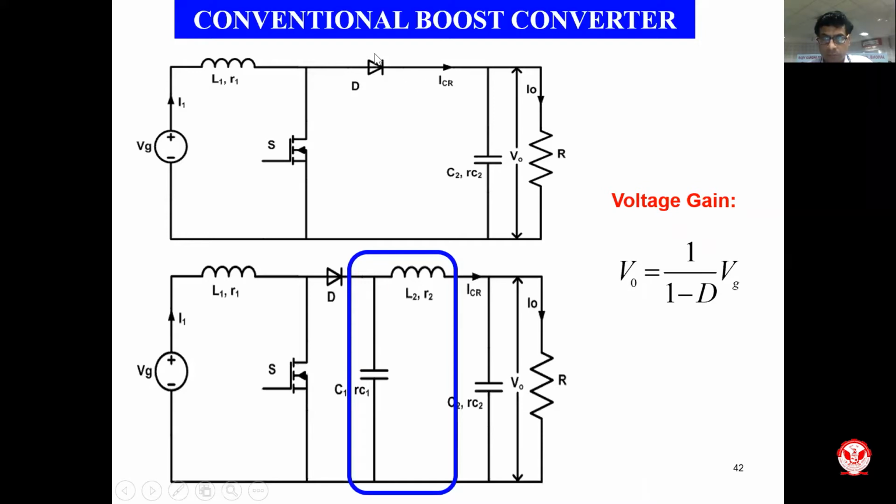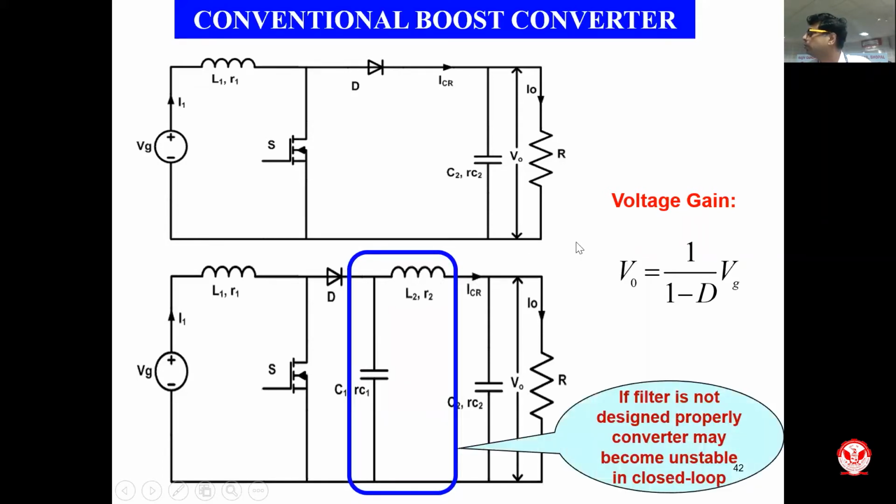Once this diode is off, the current ICR is going to be zero, and as a result the current going towards the load is going to have high peak to peak ripple. At one time that current will be zero, and at other times it will be equal to the load current plus the ripple. This discontinuity deteriorates the life of the load and is not desired. So you include an LC filter so that the placement of this inductor makes the current ICR continuous, thereby improving its performance.